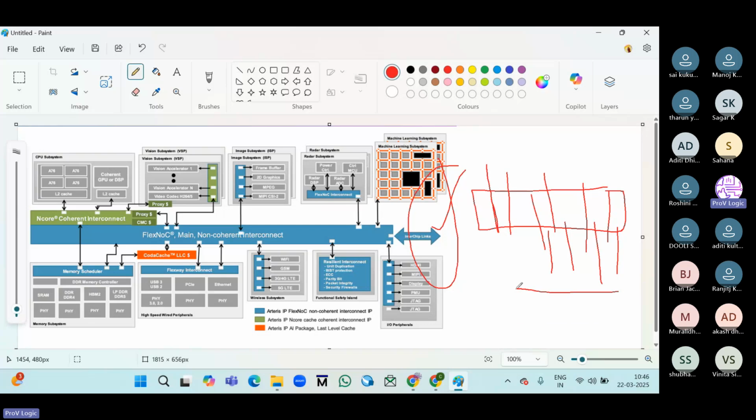But if you go to PCIe, we connect a number of lanes. That means the 16-bit data will transfer serially, but across lanes. Okay. So you understand now how the speed is increased by using PCIe, right? And also it eliminates the shared bus. We don't have the shared bus. It will communicate point to point only, using multiple lane configurations.